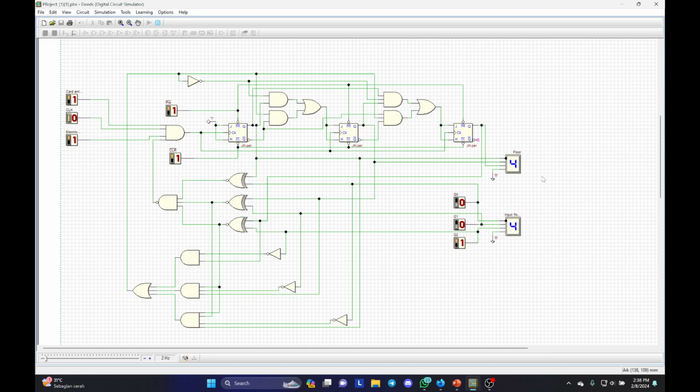And also the lift goes down because the comparator in section C dictates that section A, that is the fifth floor before this, is greater than section B, which we inputted as the fourth floor. So 5 is greater than 4, so the comparator outputs 1, telling the lift to go down.